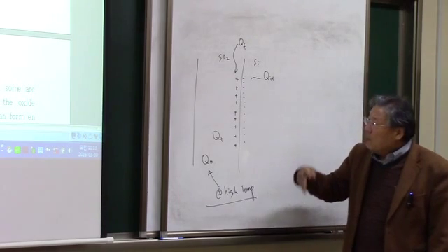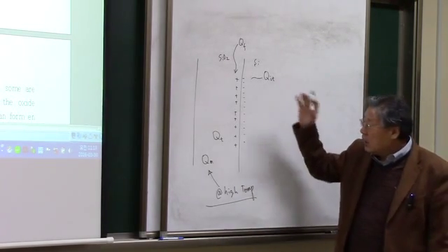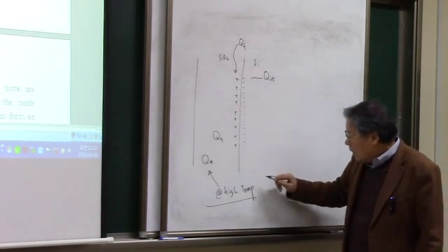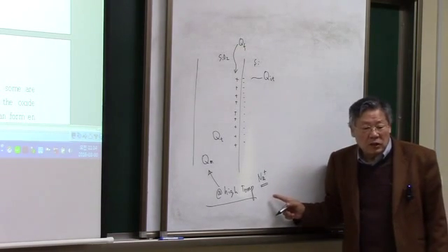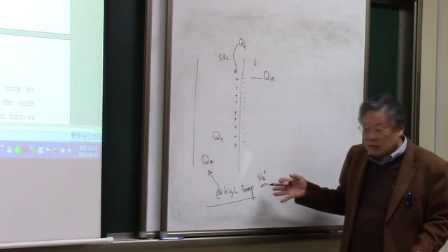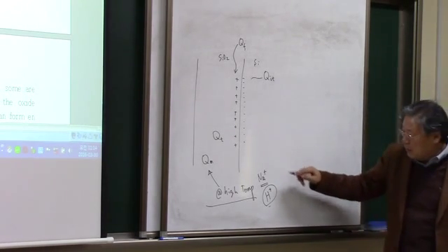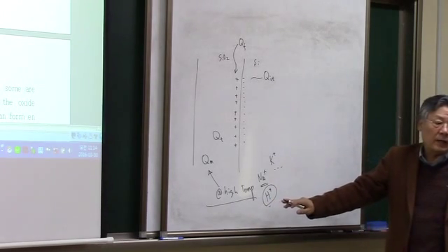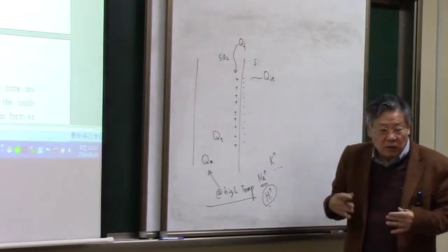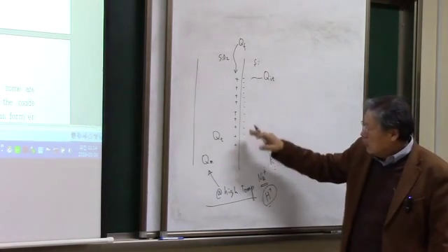But when you elevate the temperature, like during the oxidation, the temperature is about 1100 degrees centigrade or 1000 degrees centigrade. At that high temperature, these mobile charges are very mobile, and typically sodium, which comes from our sweat, a sort of contamination, and hydrogen, and potassium and so forth, are very mobile at high temperature. So these mobile charges are going to be incorporated in the oxide during the oxidation process at the high temperature, okay? And it affects the electrical properties of the transistors.